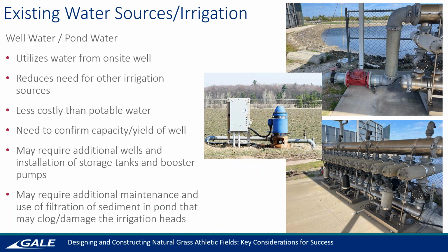You need to confirm the capacity and the yield of the well that you're installing. You need to get a well contractor out there to do some tests, see what's going on and what you can get out of it. Depending on what you're trying to irrigate, is it one field, two fields, or more? Obviously, you may need additional wells, and similarly to before, you might need a booster pump and storage tanks and things of that nature.